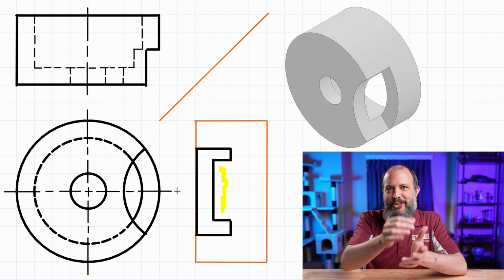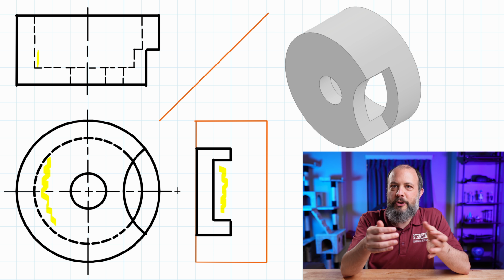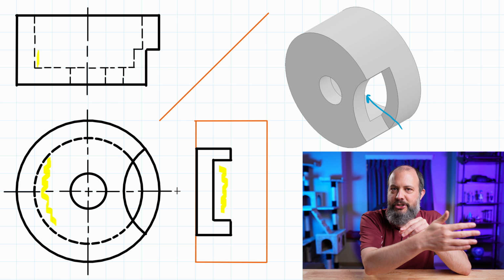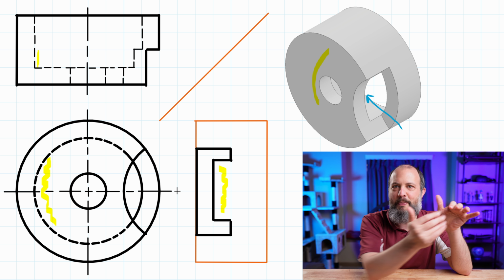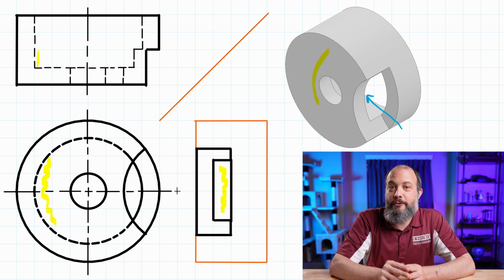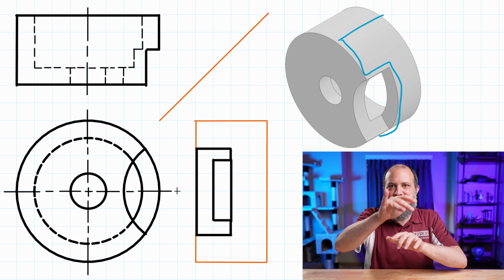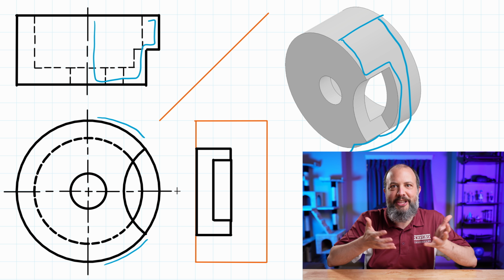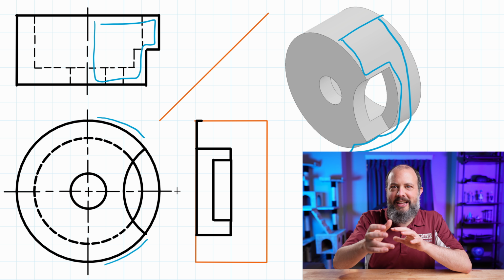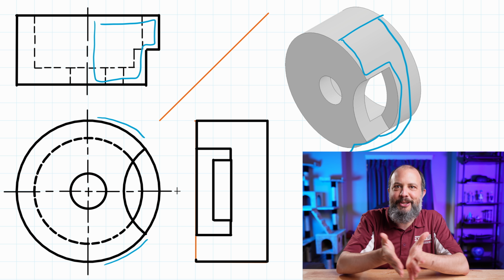And then the center of this C section will be a small vertical rectangle which is looking all the way through the part to the solid inside section of the back of that inner cutout. Of course, I skipped over most of the visible side. Of course, the big round cylinder, you can see, again, another C shape all wrapped around the edge, right? Vertical on the right side and then horizontal along the top and bottom. That's the main outer part of the cylinder that you can see.